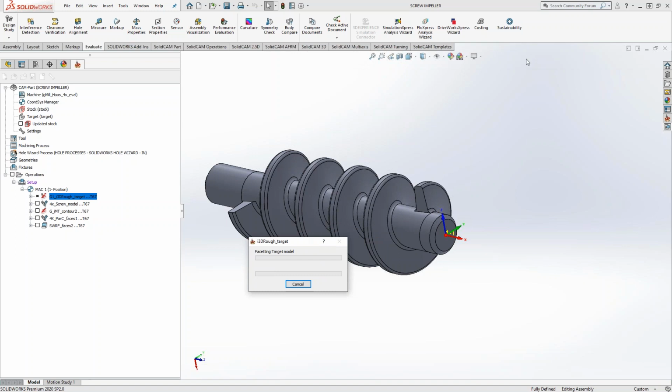Okay. So what I'm going to do next, just so we can talk over the fact that this thing's calculating, is I will put in an index. Either I can set up another coordinate system, so I can tell it that I want to come from the other direction, or I'll put a transform in there. If I put a 4th axis transform, I'm essentially telling it to do the toolpath from the other side. But since this is still a recognition toolpath, it should recognize the geometries and automatically do it. But to be safe with the 3D iMachining, I think I'll just put in the index position, only because I want to make sure that it's looking at it from that angle, and also take the opportunity to show you how you could do that on this 4th axis part, if you guys weren't already aware.